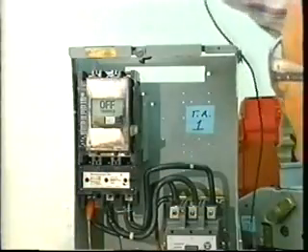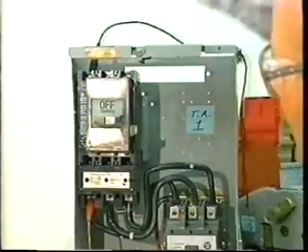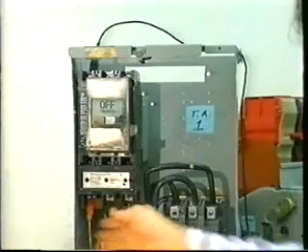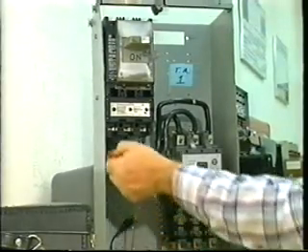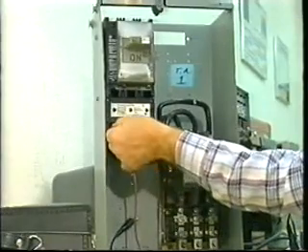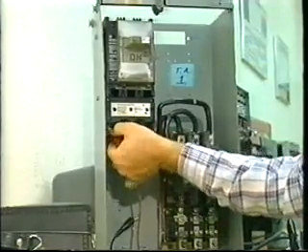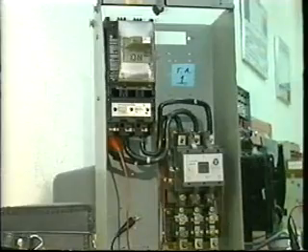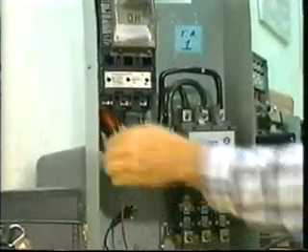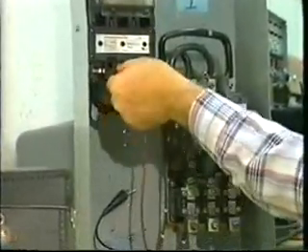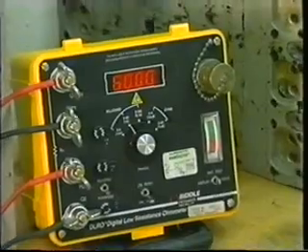An insulation resistance test is made between line and load terminals of individual poles with the circuit breaker contacts open, between adjacent poles and from poles to the metallic supporting structure with the circuit breaker contacts closed. This test may be performed with the circuit breaker bolted to a metallic base, which simulates the in-service mounting.